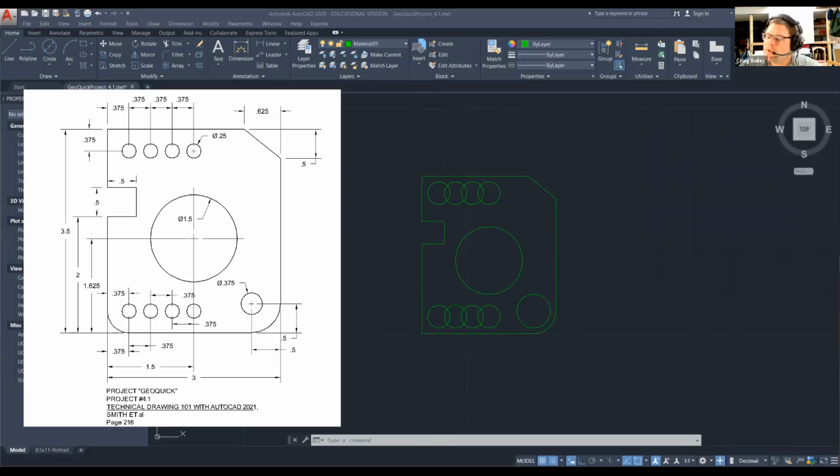Fair enough. When you start the command out of the box, fresh from the command line, the computer is defaulting to expect the radius. We have to do something to switch it into the diameter mode. So start the circle command from the command line, please. Good.